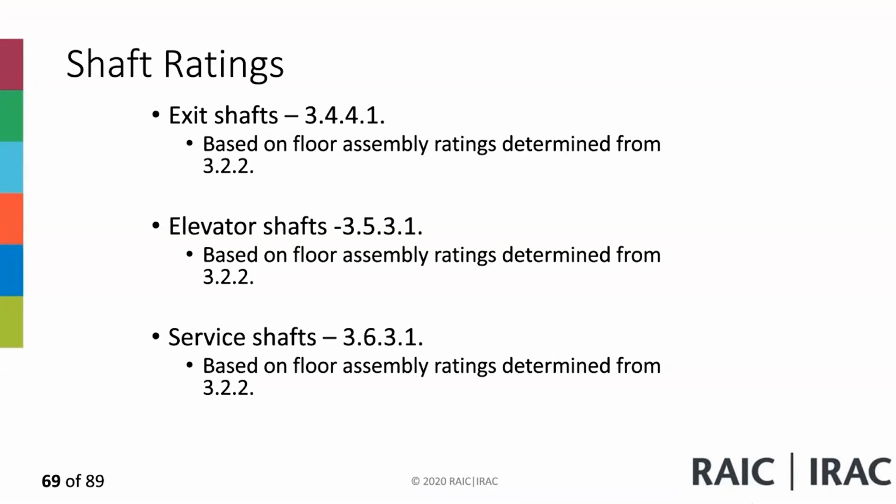Sometimes you don't have a requirement for fire resistance rating, and you have to default to a 45-minute rating. So your exit shaft will always have a rating, even though sometimes your classification in 3.2.2 does not require it. Then you apply the 45 minutes if there's no requirement for floor rating. For elevator shafts, let's go to 3.5.3.1.